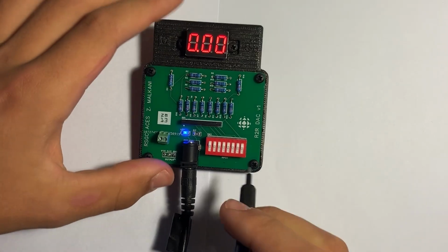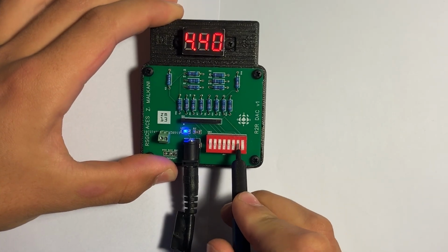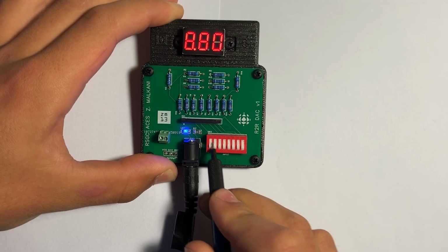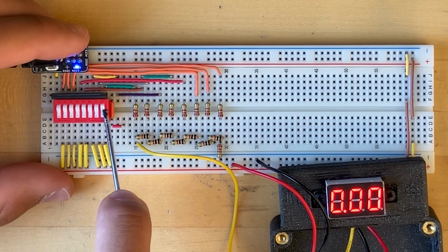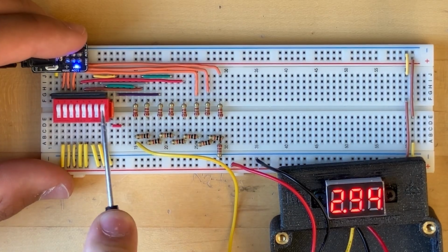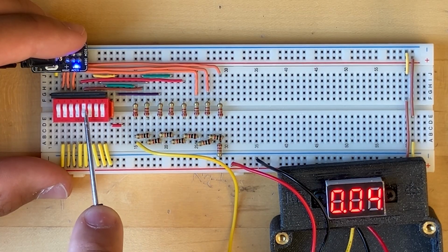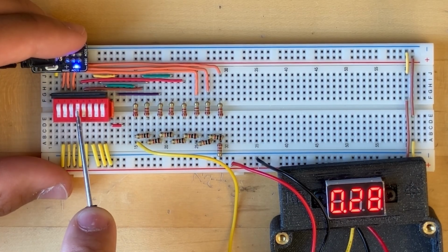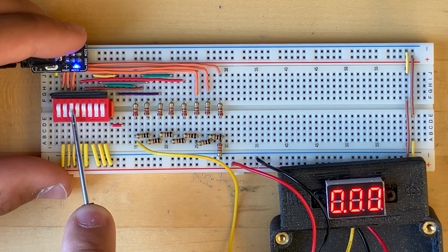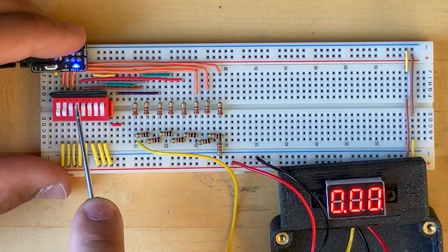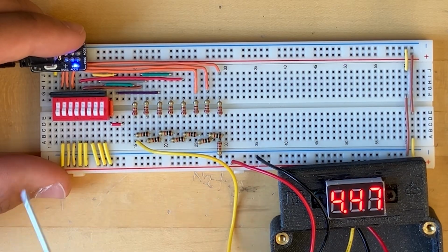Now all inputs will be set to high to show the max voltage that has been used during these tests. This is the same demonstration on the breadboard prototype version when being supplied with just over 5 volts. The voltage output on the breadboard prototype can be slightly inaccurate because the resistors used are ±5% tolerance rather than the ±1% tolerance used in the final device version.